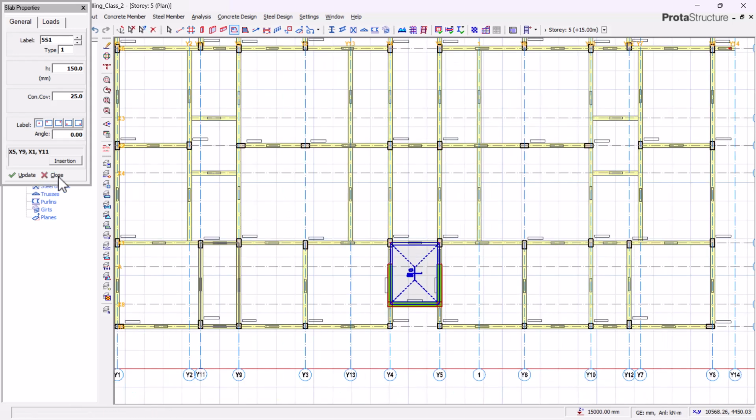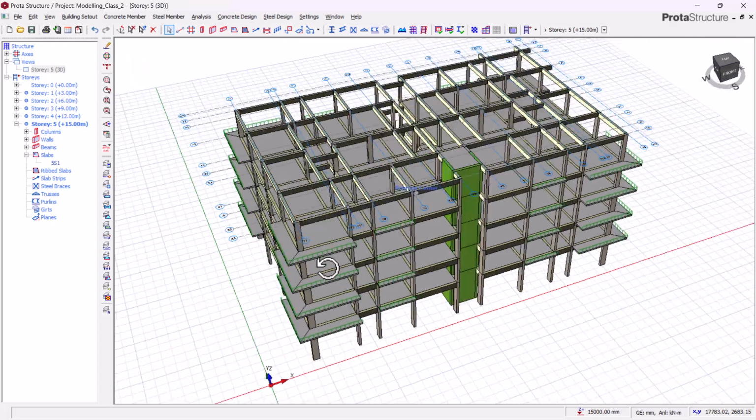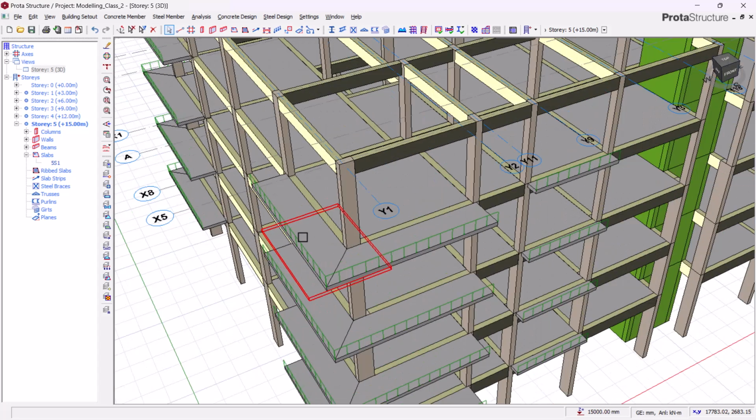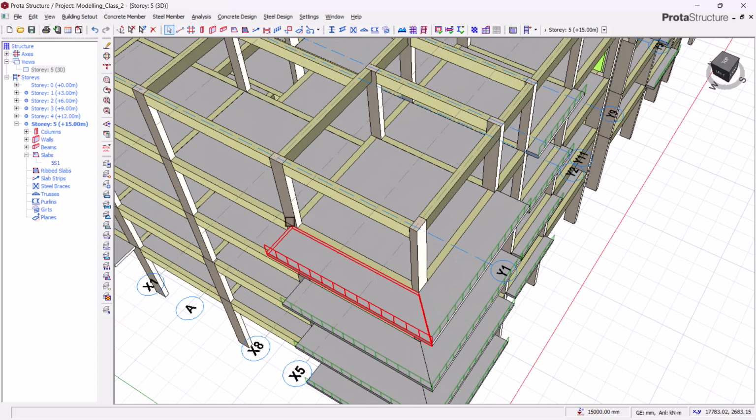Keep in mind that at this point over here, we need to provide a cantilevered beam. We have to provide a cantilevered beam that will carry the roof that is coming at this very point. Remember, this is a cantilevered slab, so we have to protect this place with a beam in order to carry the roof coming at this very point on the roof level.